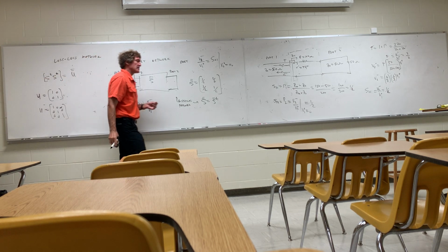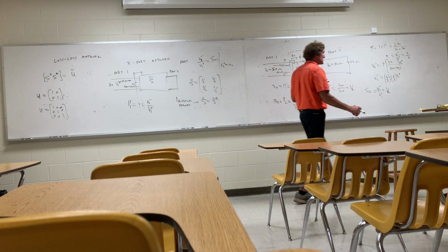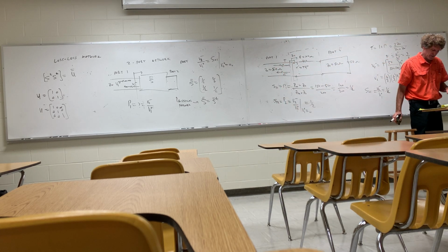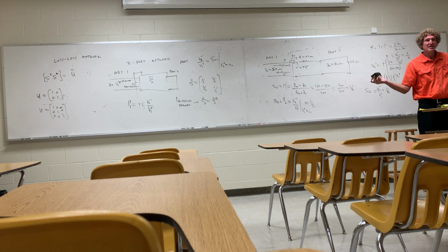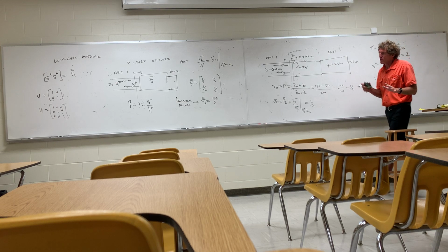And he'll have that in his book. So if you multiply the transpose times the conjugate of the matrix, you're going to see, if it's all ones on the diagonal, it's a unitary matrix, and if it's all ones, it's lossless. To me, that doesn't matter. I don't care. I really don't. When you measure these things, this might be important.